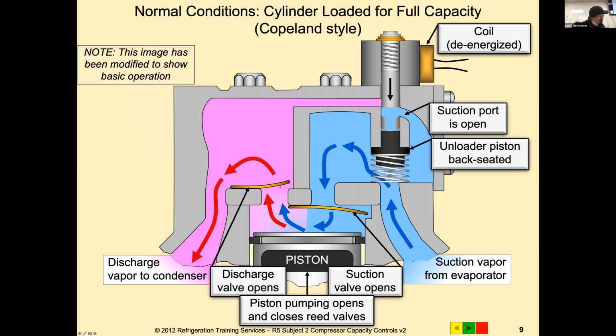So can you see that compressor, that discharge reed right there? Yes. So if you guys have ever pulled a valve plate and you've seen that discharge reed is quite a bit more robust than the suction reed. So it's under spring pressure. It takes a lot of pressure to push up on that reed and open that up. So when you guys have discharge feedback, when you isolate and you check those valves, if you're getting any pressure coming back into your suction side, that's why you have bad valves.